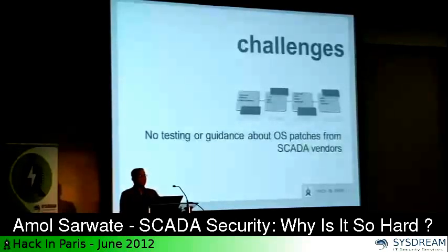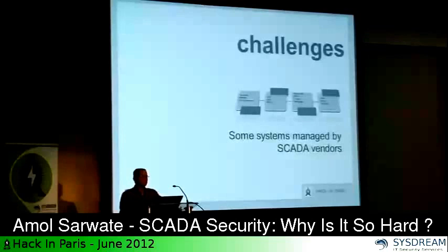Another thing, as we already mentioned, is that there is no testing or guidance on OS level patches from SCADA vendors. Some systems are managed directly by the vendors. We went into one such installation, and the SCADA owners said, this is a Windows system, do you want to audit it? And we said, yeah, we have seen a lot of Windows systems. What's the administrative password? And they didn't have the password, because the systems are directly managed by the vendor. So it's difficult to perform an audit, not really a pen test, without causing any harm to the system.